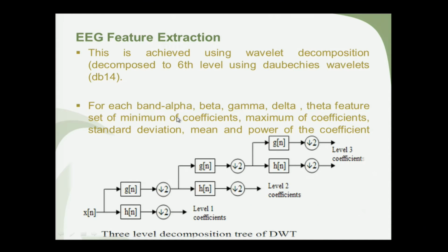For the feature extraction, we used a wavelet to decompose the signal. You have a low-pass filter and a high-pass filter which go into the wavelet decomposition, which is filter bank theory. We went with 3 levels of decomposition and we used the Daubechies-14 wavelet. Dr. Ingrid Daubechies is a mathematician who worked on wavelets, and there are hundreds of wavelets in her name.